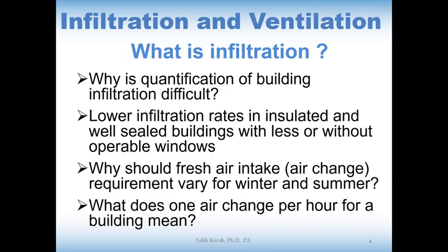Okay, this is gonna give you the CFM. So again, volume times air changes per hour divided by 60 minutes. Okay, so this is gonna be the CFM value. For this example that I just told you, like a room with the measurements 9 by 12 by 8, and with an air change of 1.5 per hour. So what's gonna be the value?